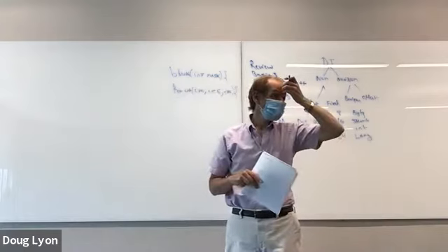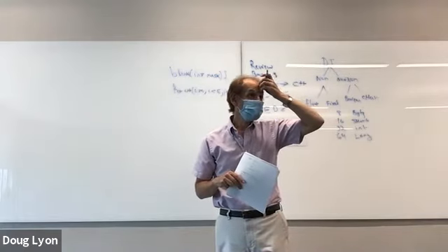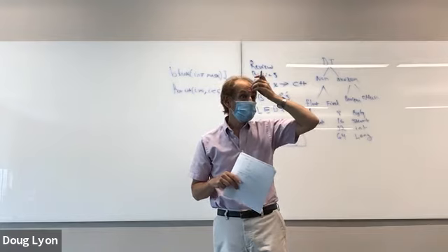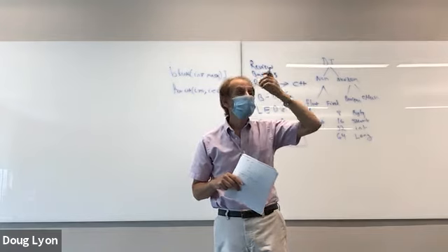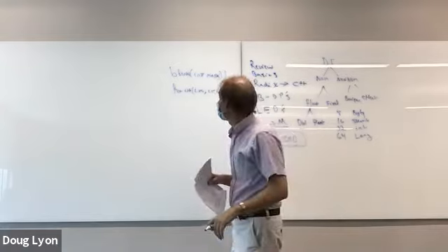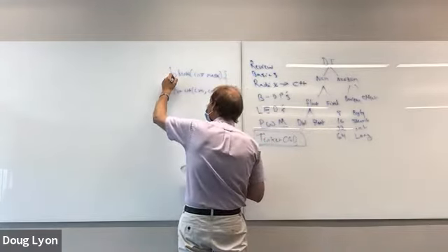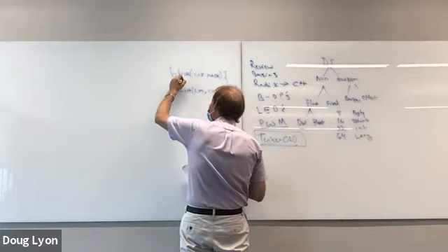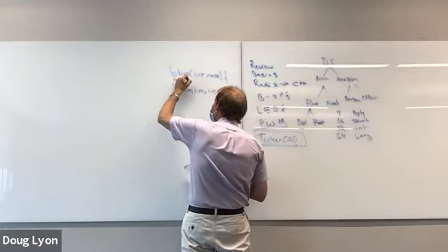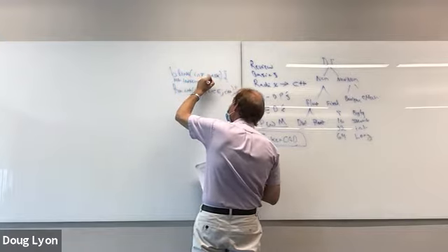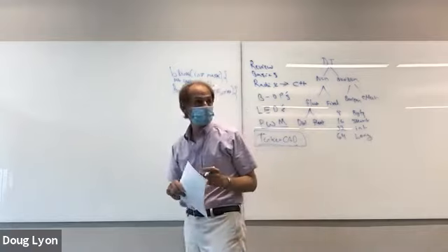what you want to do is figure out what the least significant bit looks like, then shift it over, and then figure out what the least significant bit looks like and go to the next LED. So if your LED index is set equal to integer LED number equals 13, because that's the port number that you're going to use for your output.